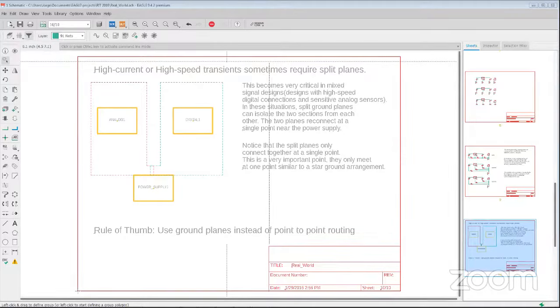Okay, very well. Now we also have somebody on our Zoom saying, is it possible to do length matching of segments of this for the same net? For example, with DDR3 flyby topology. It is possible. What you can do is, in the meander command, you can specify a length.